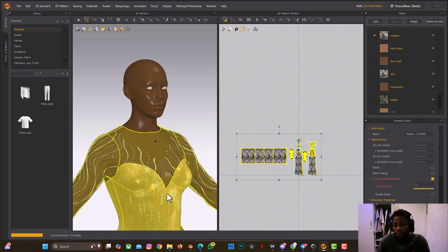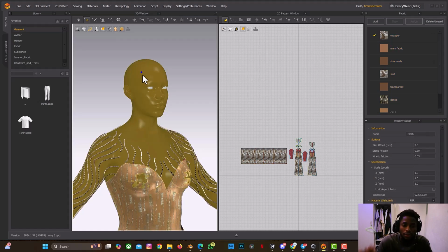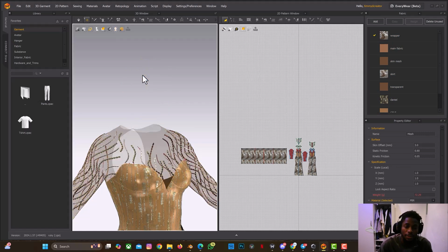You need to reduce your particle distance to get smooth wrinkles when your cloth is animating, but it depends on your fabric. That will determine the value you want to use for your particle distance. The next thing I'll do is to delete this character. This is an OBJ file, so it's not animated. So I'll select this and delete.